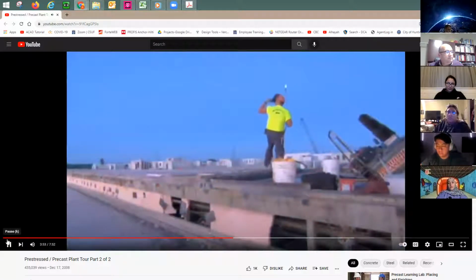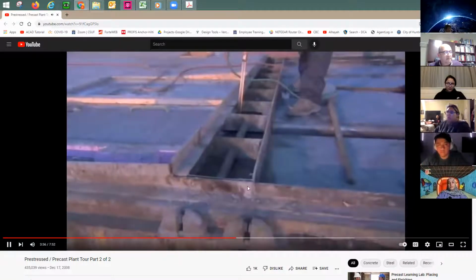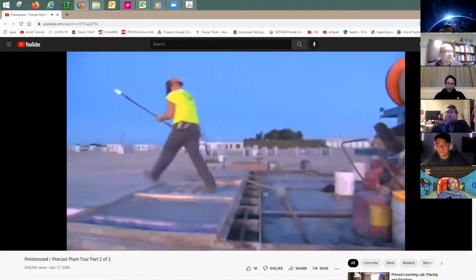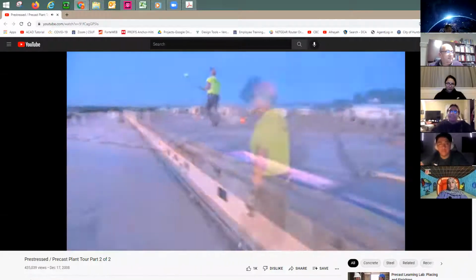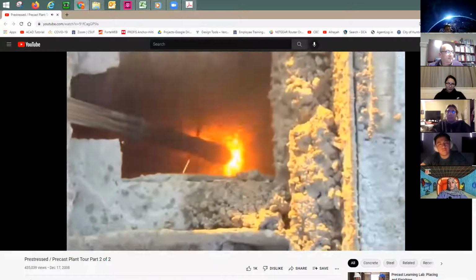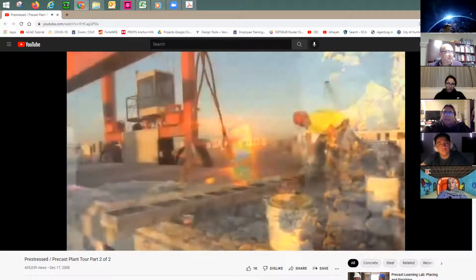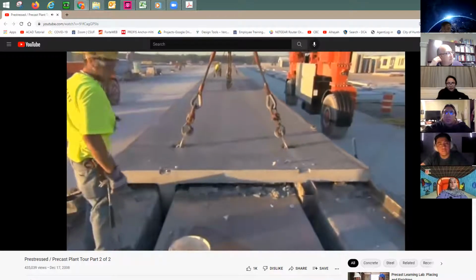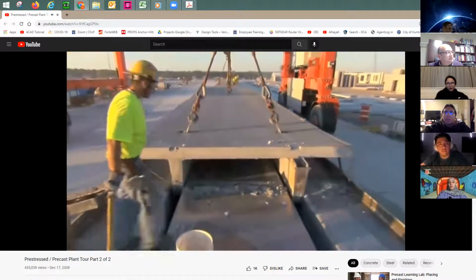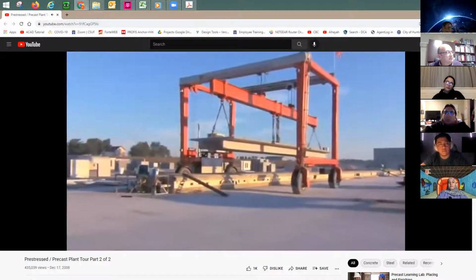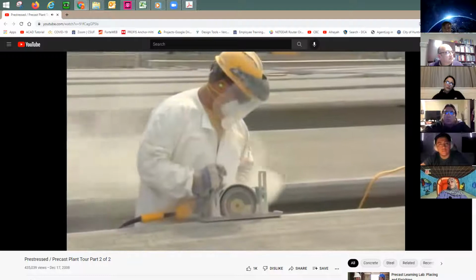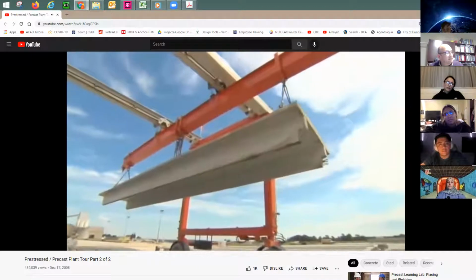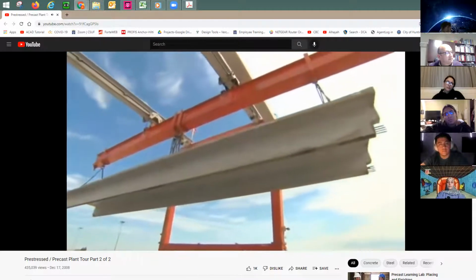The strands are detensioned in a specific sequence established by the QC department or the plant engineer. Here, personnel are positioned at each end of the bed and at some of the intermediate bulkhead locations. On a signal, they burn the strand at each end. After all the strands are cut and block-out formwork has been removed, the Ts are stripped from the form. Cables are attached to the lifting devices, and each piece is removed and transported to a detailing area for any minor cosmetic touch-ups. Also at this time, the QC department does a post-pour QC check on each piece that is brought to the detailing area.